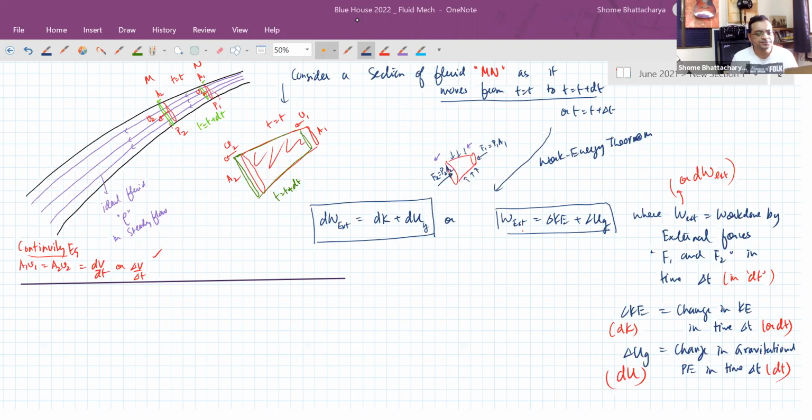Yeah, Samar, to answer your question, whether the liquid is flowing up or down, if the cross section of the pipe is uniform, the continuity equation will tell us that the speed of flow is uniform. So that means it's a non-accelerated motion, which means the net force should be zero. So pressure at a lower point should be higher, pressure at a higher point should be lower. So the same kind of pressure gradient will come. The difference will occur if the cross-sectional area is not uniform, because then the motion of the fluid elements is not uniform motion, it is accelerated or decelerated motion.